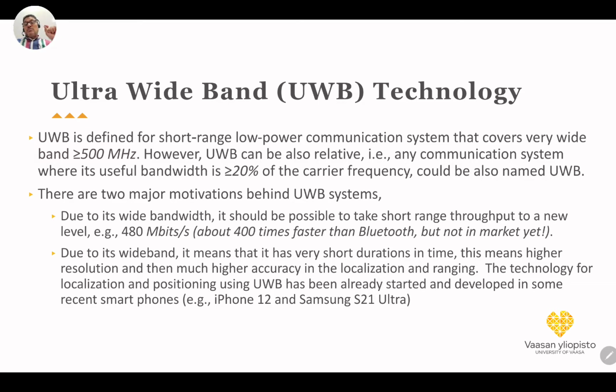So to achieve this 500 megahertz bandwidth, it can be realized with an impulse with a width of 2 nanoseconds, which is a very small duration. So if you generate an impulse with a width of 2 nanoseconds, it will occupy a bandwidth of 500 megahertz.